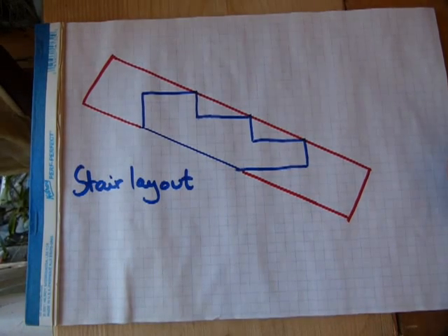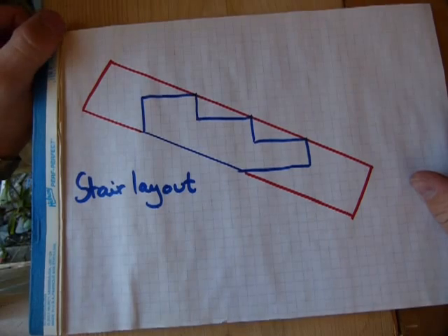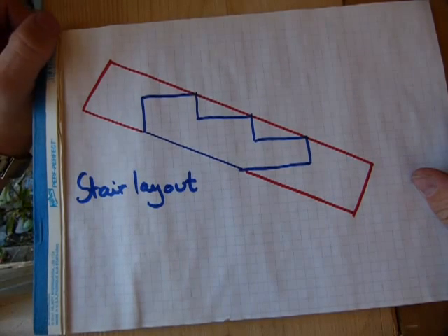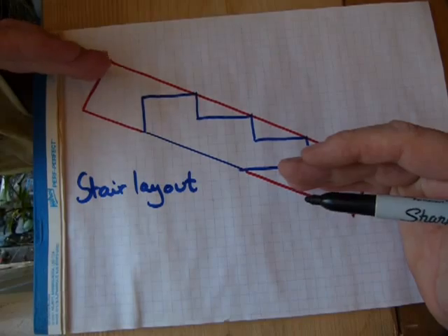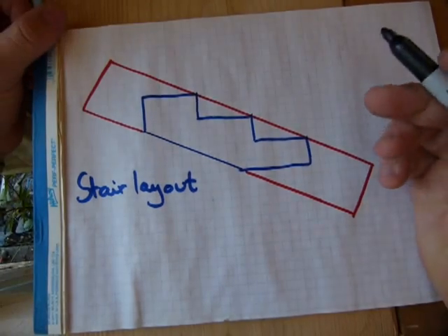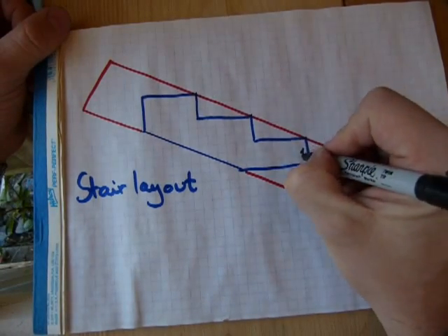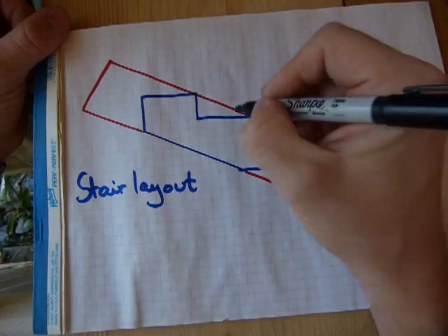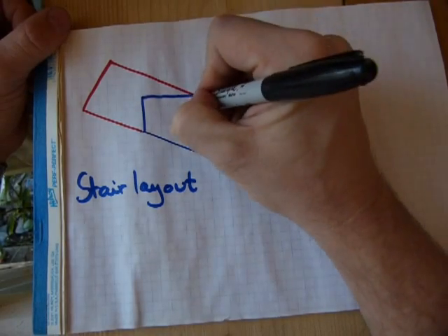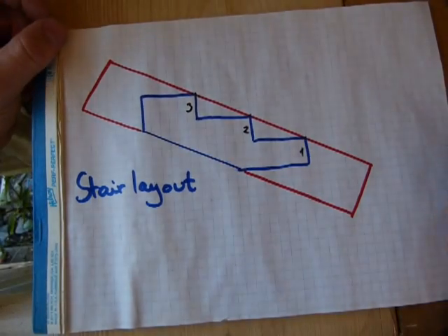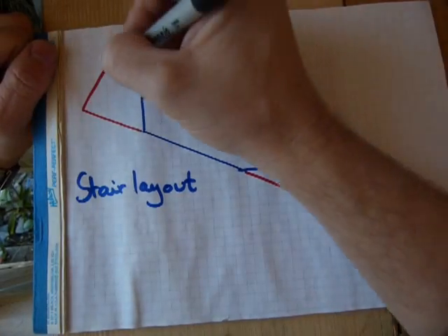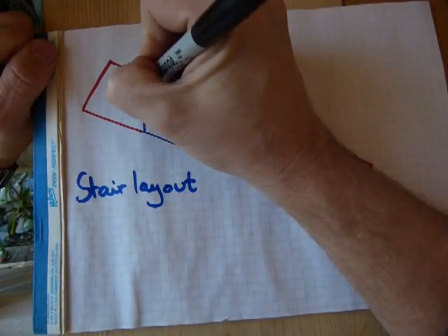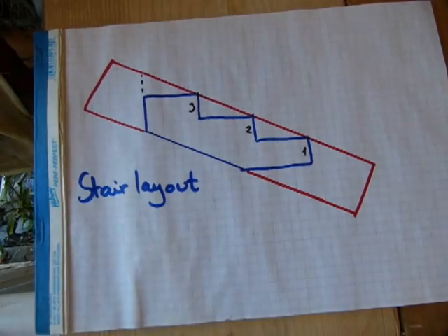You recall that in the stair calculation we calculated that we're gonna need 4 risers to go from the floor to the top of the landing. You see here on the finished piece 3 risers. The first one there, second one there, and the third one there. There's no mistake here. The 4th riser will be here, where I put the broken line there.